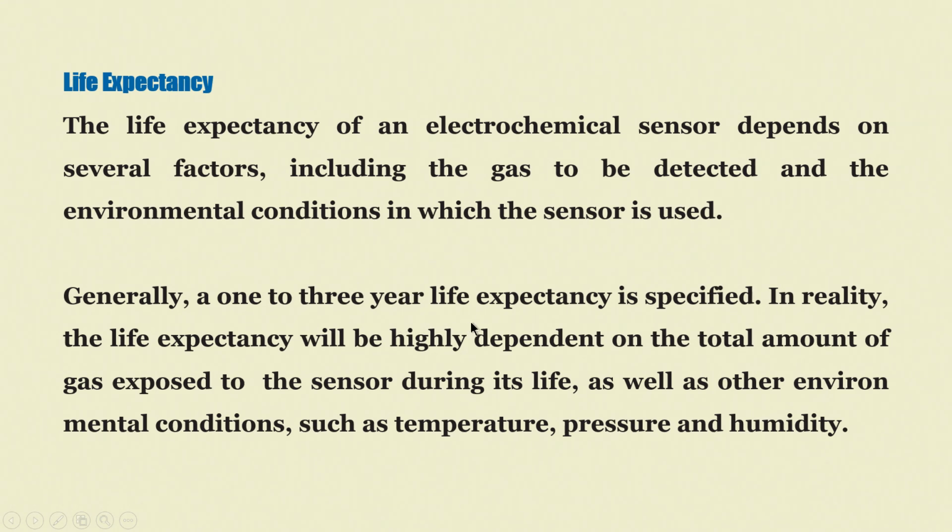Generally 1 to 3 year life expectancy is specified, depending upon the manufacturer also. In reality, life expectancy is highly dependent on the total amount of gas exposed to the sensor during its life, because there will be a tiring effect. The sensor will get tired of doing its duty.